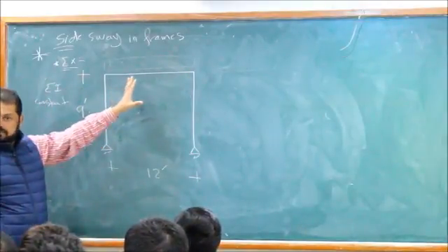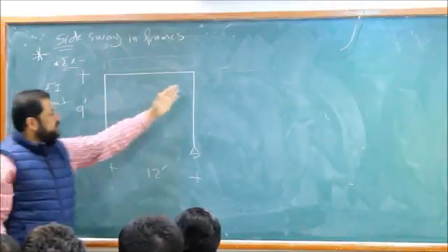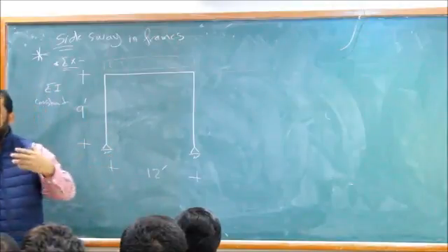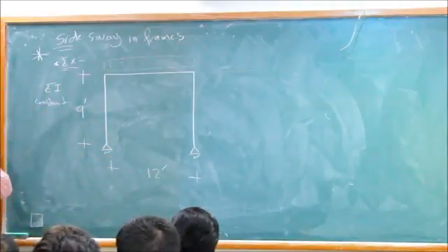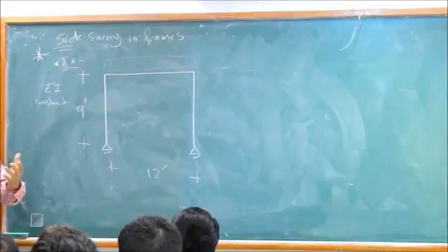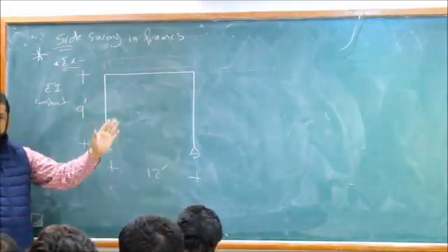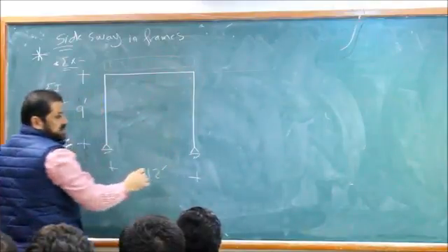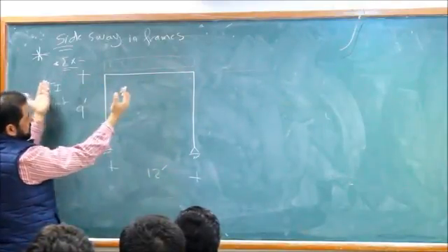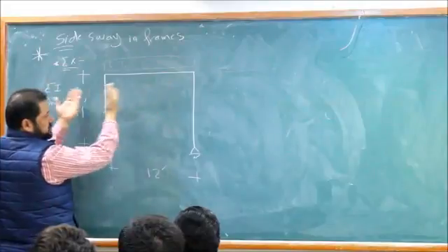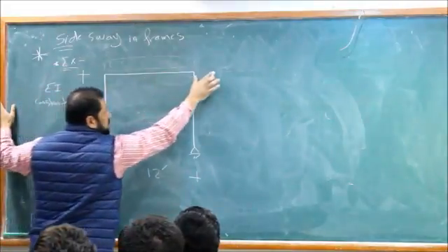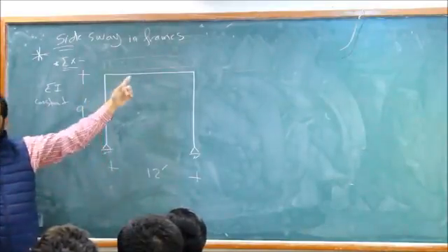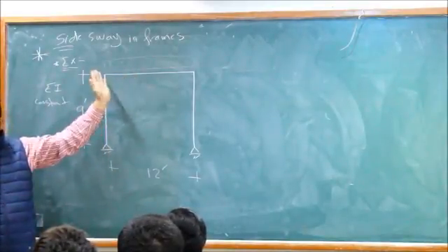Look, a shear wall. If this one wants to move, the shear wall will hold it and prevent the movement. Okay. These are lateral systems. We use them in lateral design, earthquake design, and some high wind design. You may use X braces or something else. Or you may have just something like this. But is there anything that prevents the side movement or the sway? Nothing. But under this loading, there will be no side sway.